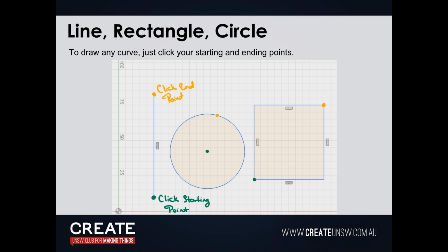Or you can also do this. You can do sketch dimension. That shows you the dimension of that. Now that's set. So if I want to change that to more, just hit 70 mils, and that shifts it up. That is still defined as 50 mils, but it's actually 70. And go back into that. So we'll just draw a line again.